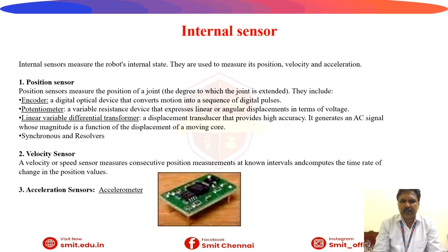Then the linear variable differential transformer, a displacement transducer that produces high accuracy. It generates an AC signal whose magnitude is a function of displacement of the moving core. So it generates the AC signal, whose magnitude is a function of displacement of the moving core, up to what the core is moved. From that we will find out the accuracy, the displacement transducer. Then synchros and resolvers.